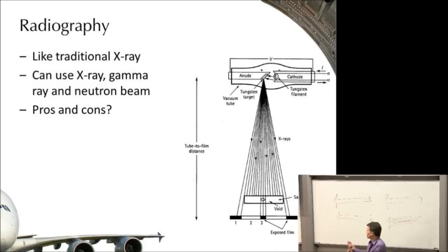Yeah, you've got an X-ray source. And if you know that denser materials absorb X-rays more, to get through a metallic sheet, you're going to need to have very high intensity X-rays. So you're going to have this crazy powerful X-ray source floating around, pumping out X-rays, and X-rays just don't stop because they feel like it. They will stop if they're absorbed, but the ones that miss your target are floating off to hit anyone else who's walking around as well. So it needs to be done in fairly controlled environments. So you've got to be careful with radiography.